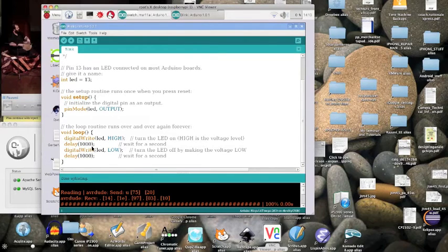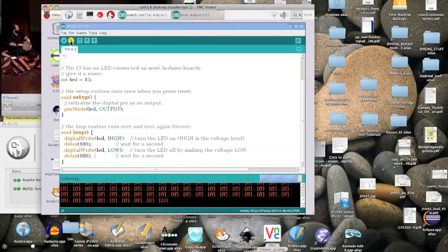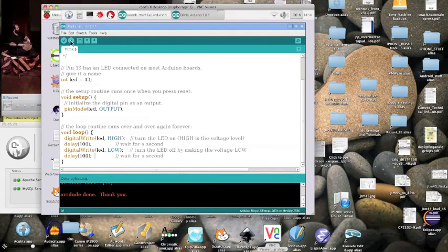Now if we want to speed up the on and off transitions, how would we do that? Well, all we've got to do is change that from 1000. Let's say change it to 100 instead of 1000. Now we've got 100 milliseconds. So now if we compile it again, let's see what happens. What we're doing now is replacing the earlier program with a new program that's going to be burned onto the Arduino.